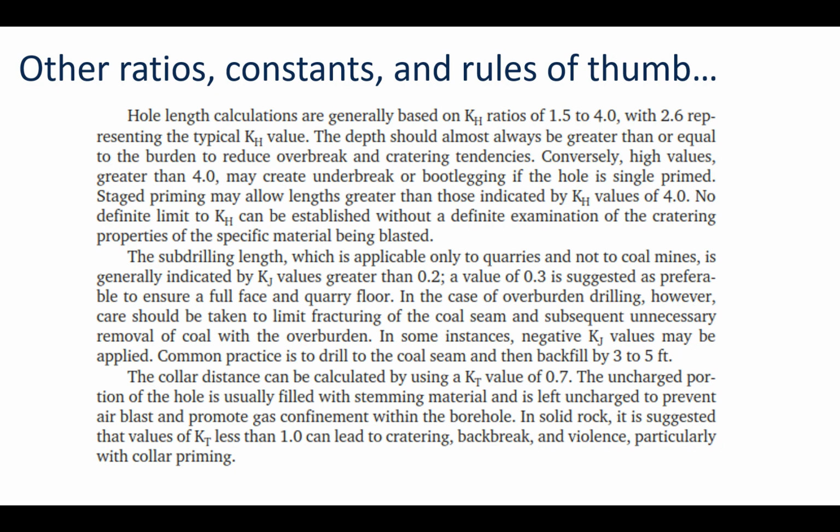And then collar distance can be calculated using K sub T values of 0.7. The uncharged portion of the hole is filled with stemming materials, so it prevents air blast and promotes confinement.